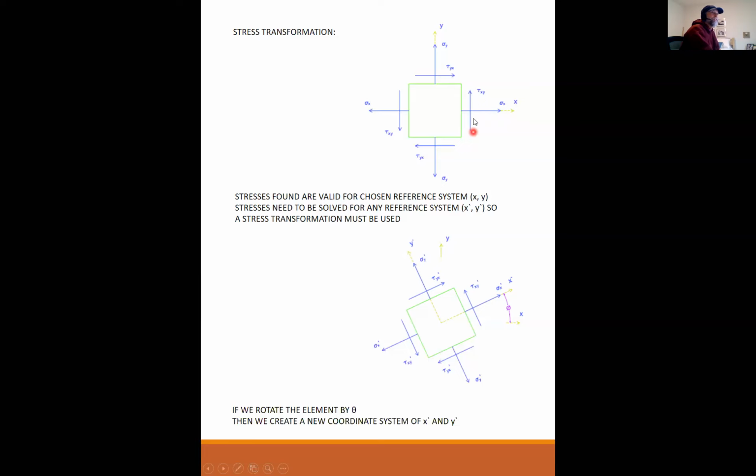That gives you shearing stresses. But you may have a material that is sensitive to tensile stresses, maybe. And in this coordinate system, you don't see your worst tensile stresses. You have to rotate this system to capture the worst compression or the worst tensile stresses. That's why this can be important.